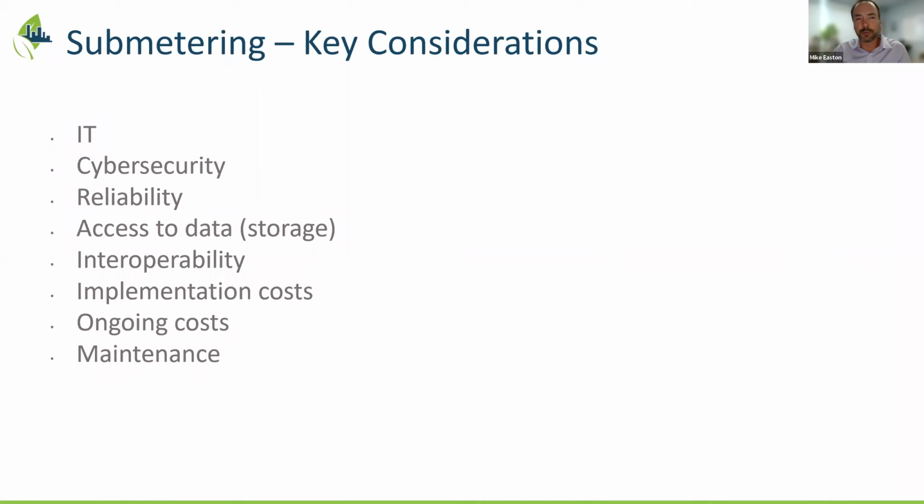We talked a bit about communication challenges as well. And if you're not getting data out of your meters, they're really irrelevant to your building automation system or your energy management system. So ensuring that there's constant communications with the meter is really critical, and that can fail for a variety of reasons. You can have somebody sever a hardwired connection into a meter. You can have other connectivity issues. Somebody changes some networking issues, programming.